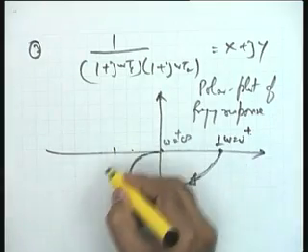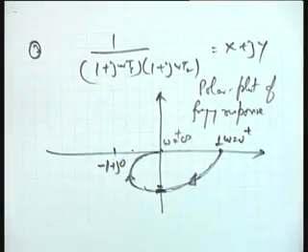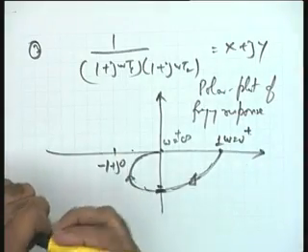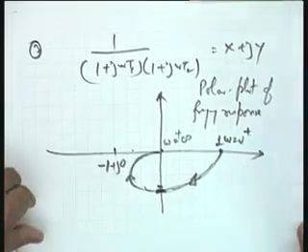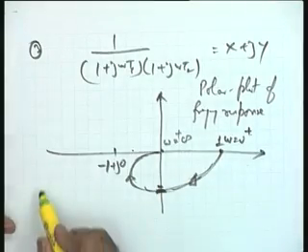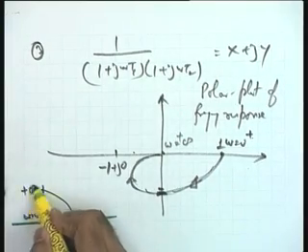Though with experience, you will slowly find that you can conclude stability right from here, because you can visualize the total Nyquist plot in mind. You need not bring it on paper, but just initially in one or two examples it will be interesting to bring it on paper as well. So, omega equal to 0 plus to omega equal to plus infinity. Let me make the Nyquist contour here. I started from omega equal to 0 plus, and I have reached plus infinity.